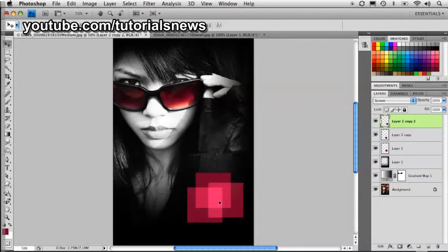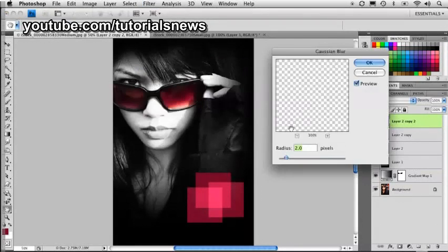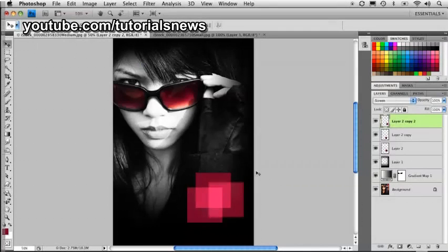I'm going to put this one right back here, but I'm going to change something about this one. I'm going to give this one a blur. Let's go under our filter and go to Gaussian blur. So it almost gives it a sense of depth. These filters and blurs, you don't always have to apply them to photos. You can apply them to objects to give your image a little bit more interest.